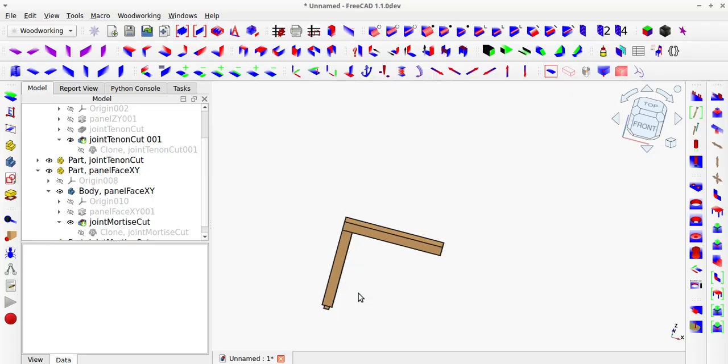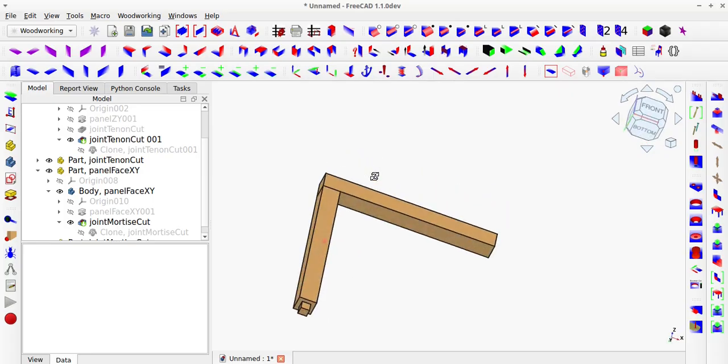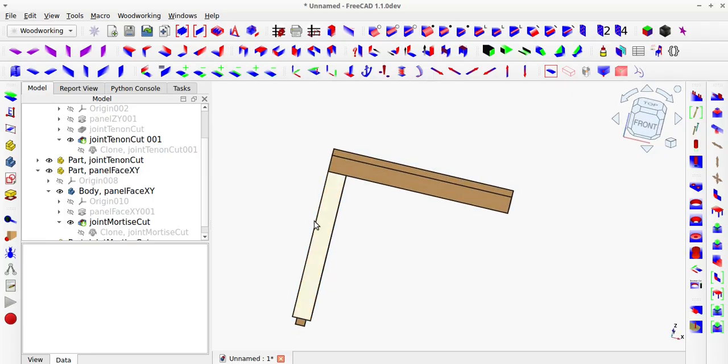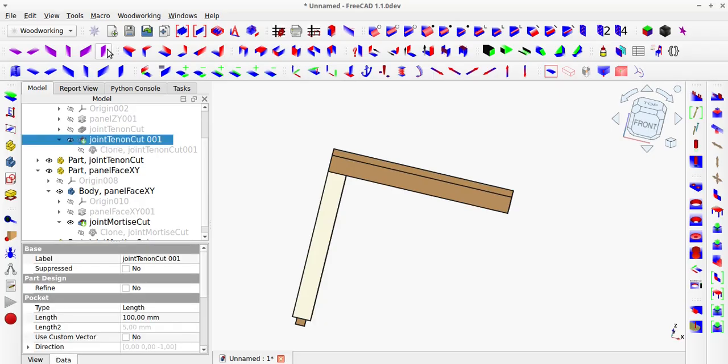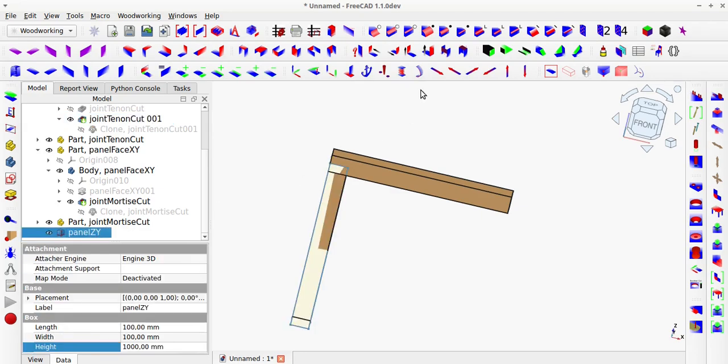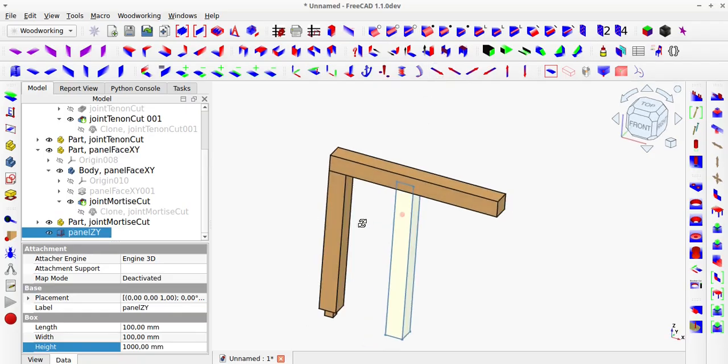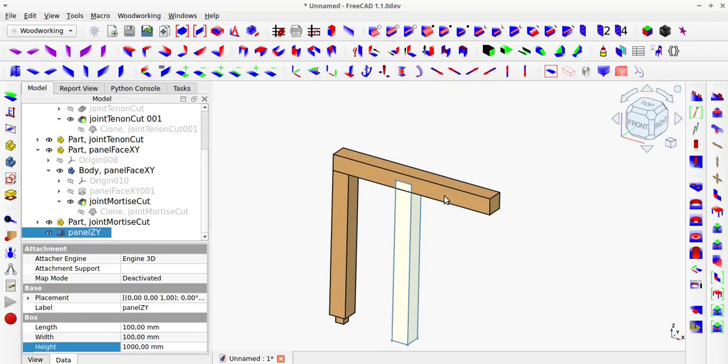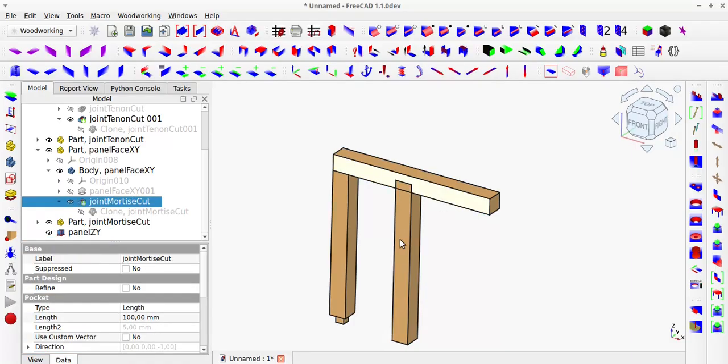Since this is also a parametric tool based on the sketch, the cutout pattern is created based on the first selected tenon face and is located in a separate container. Of course, the patterns for the tenon and mortise are different, so they cannot be combined into a single sketch. However, it is very easy to create a parametric relationship between both sketches using spreadsheet or varset, and obtaining a fully parametric model where the shape of the tenon follows its cutout.